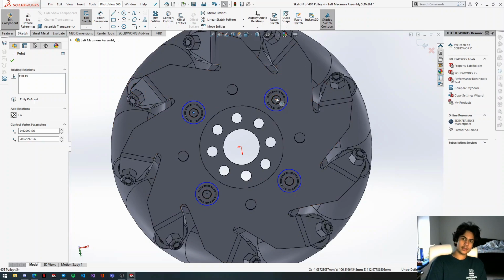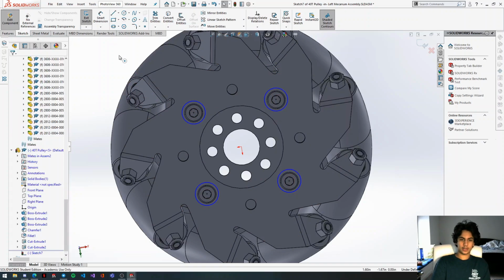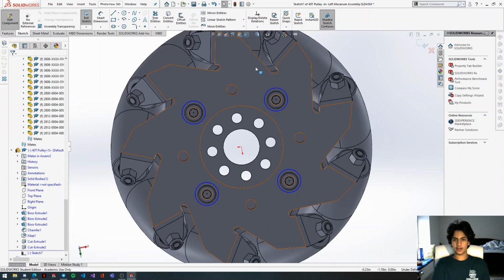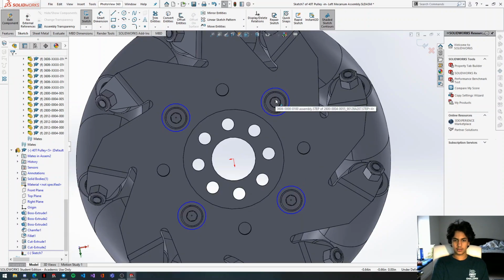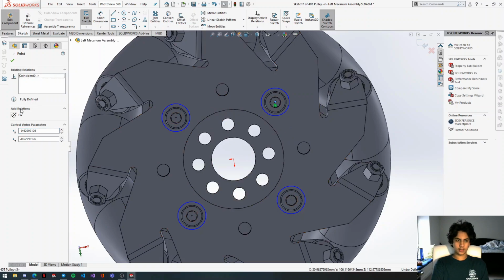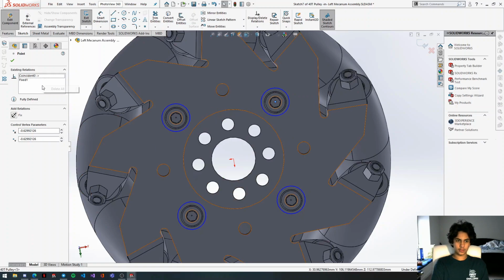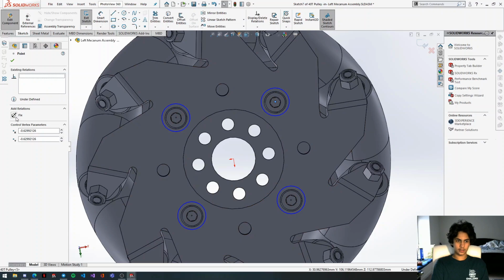What this does is it removes the relation, like the coincident, to wherever the lock nut is, which is just going to make problems for you later if you ever try to switch things up. We're just going to fix this in place. Usually in assemblies you wouldn't, because you're actually building a robot, but these are just sketches, so it's okay. So we're going to click this center point and do the same. Oops, didn't delete it. Okay, fix.